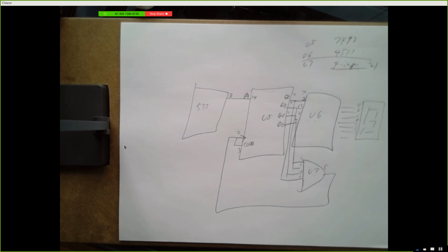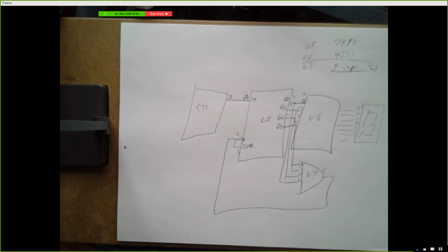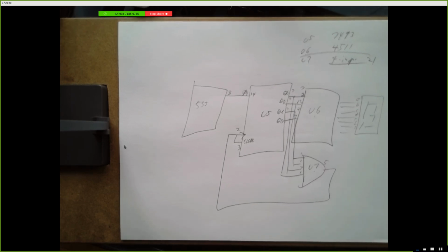Okay. Thank you. You also asked for a test plan. What is that? It's how you're going to tell if this circuit works or not. The test plan for this, since there's no switches to flip, is mostly how long you're going to watch it and what you expect to see. If you watch it and it changes from one thing to another, are you done? Are you going to say this circuit works 100%, I guarantee it? How long do you have to watch it for? What do you need to see to say, okay, this passed all my tests? So it's about thinking about the expected behavior.